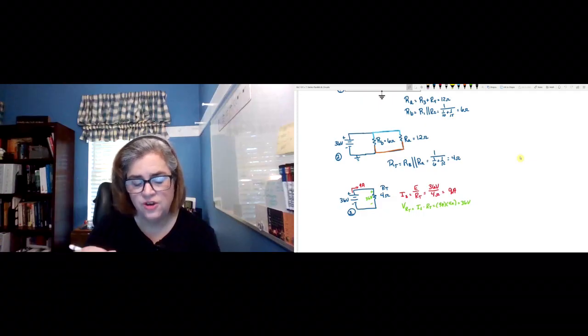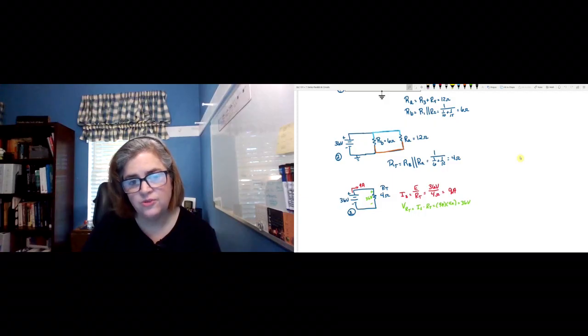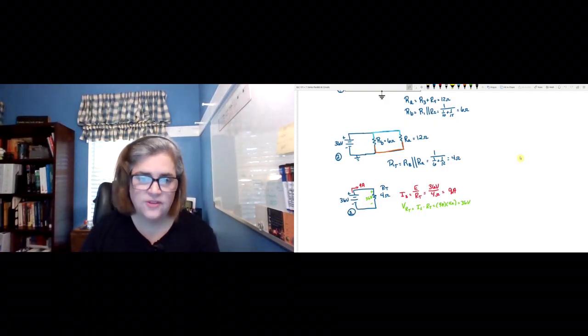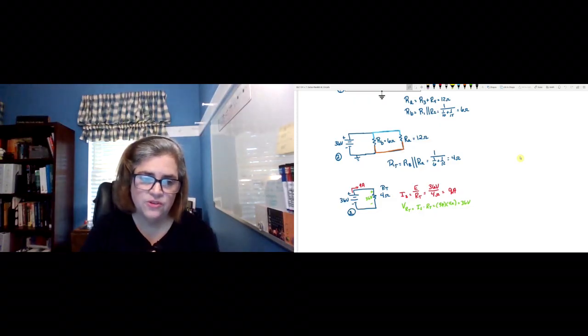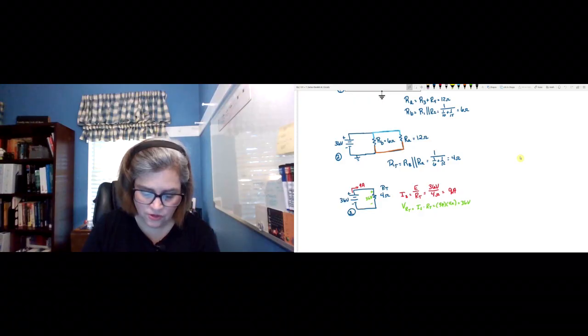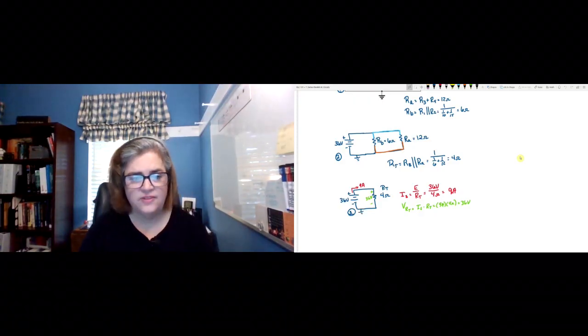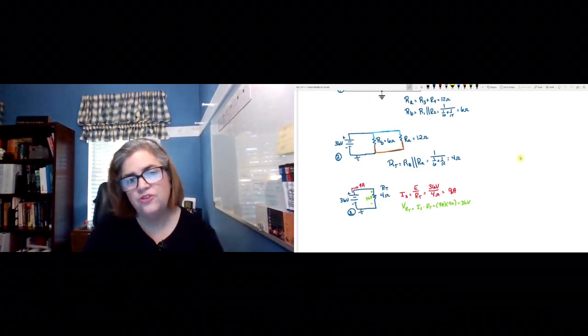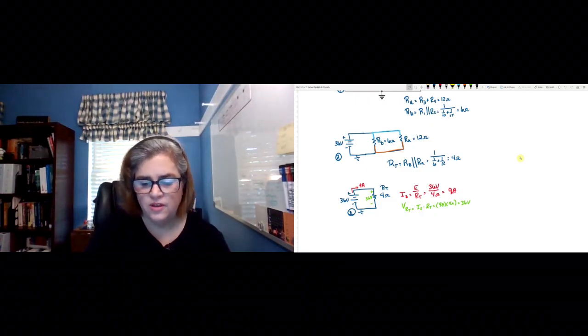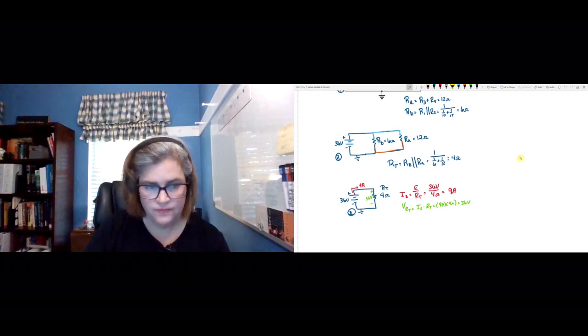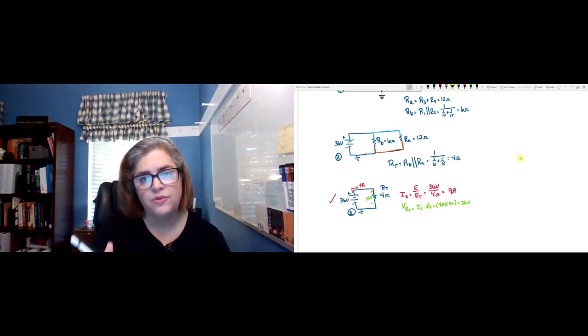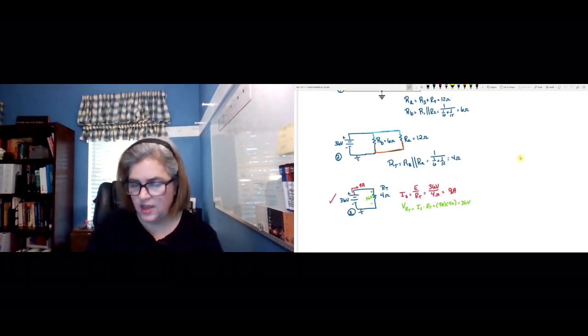That's Kirchhoff's voltage law. The sum of the voltage rises minus the voltage drops in a closed loop has to equal 0. Also, in this case, not only is that resistor in series with the source, it's also in parallel with the source because they're the only two components in the circuit. Once that's done and I have found all voltages and currents for this third circuit, now I can step back up to the previous circuit and work with it.